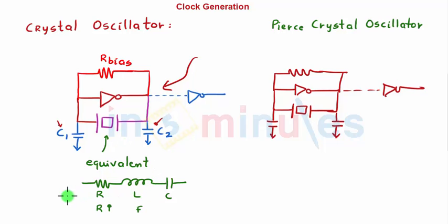The crystal oscillator can be drawn as an RLC component. The higher the value of R, the lower the frequency of operation, and depending on the external capacitance also, we can vary the value of our frequency, and the frequency stability will also vary. Remember, I'm talking in very layman's language here. The design of a crystal oscillator is itself a state-of-the-art concept, which is not needed at this point of time. What you need to understand is that a crystal needs to be connected between the input and the output terminal, and when we draw an equivalent of a crystal, it's an RLC. The higher the value of R, the lower the value of frequency. A crystal oscillator technically gives us two frequencies, the resonant frequencies, and it gives us higher frequency stability. In short, once we get a frequency, we know that we can generate a clock. That is what we are looking at in this particular clip from the crystal oscillator.